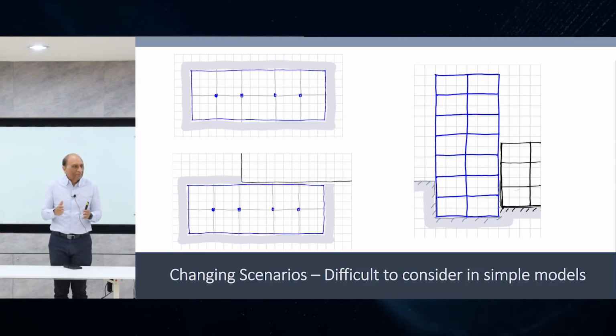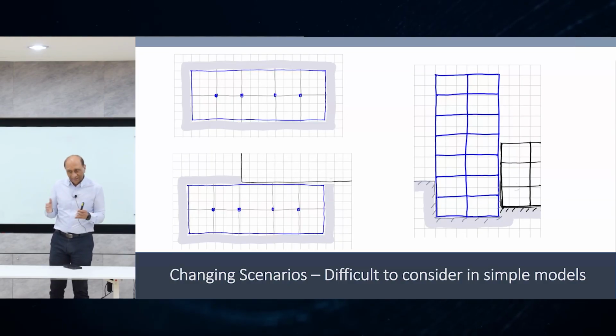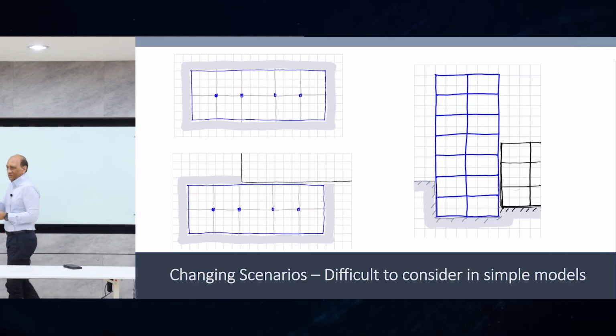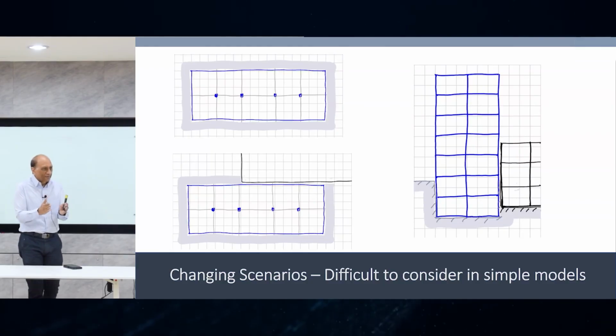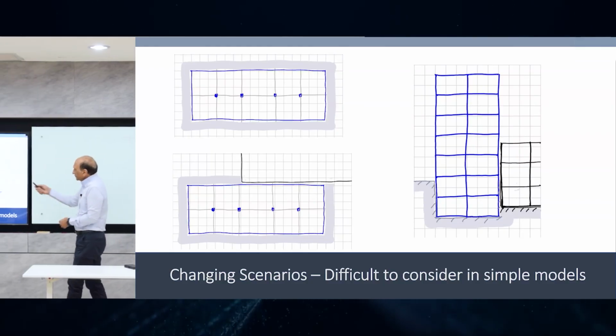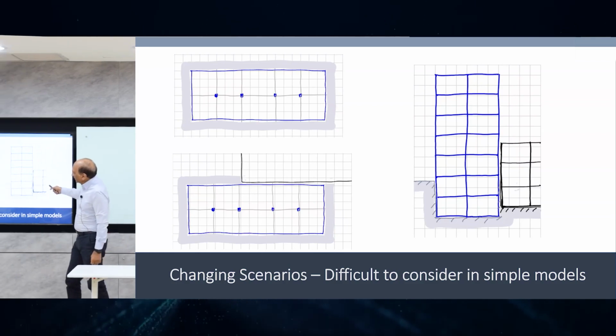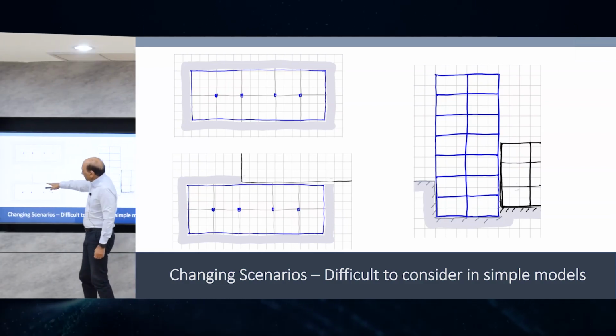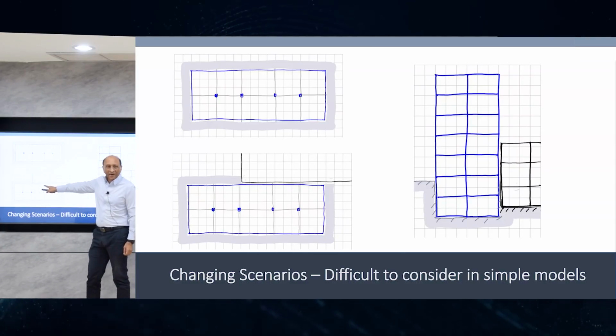But if there's a little bit of gap, actually it's not good. Big gap is fine. Okay. So the small gap is the worst. Like a 1 inch, 2 inch gap is the worst. Either you just cast together or you have a big gap like in Myanmar. Okay. So now look at the plan. It's also possible that the next building is only halfway, not the full way.